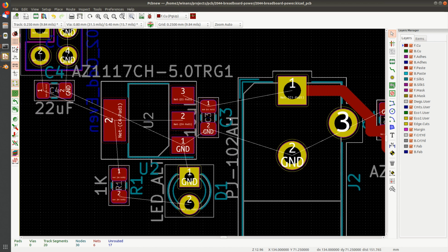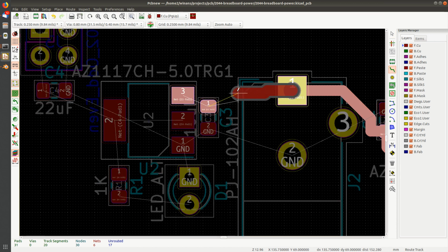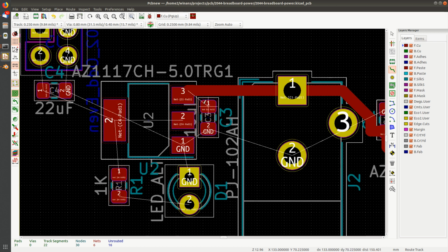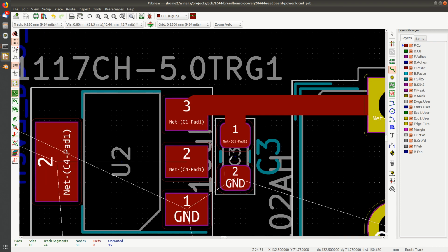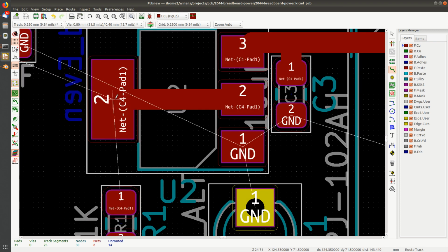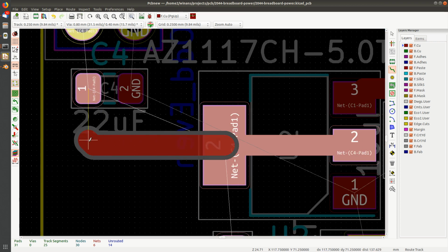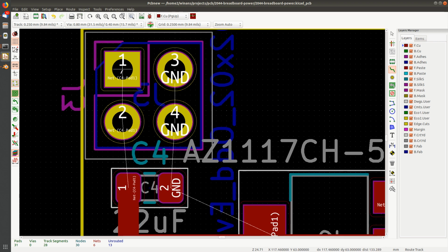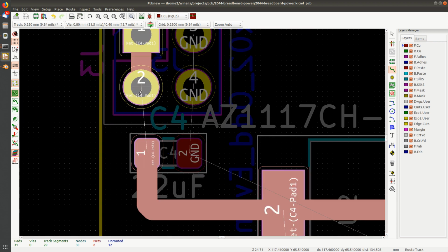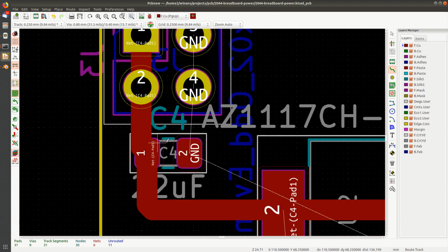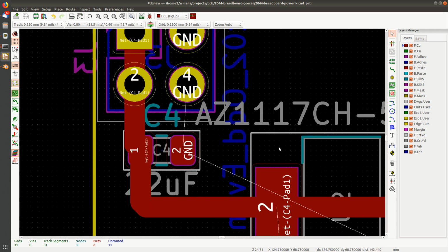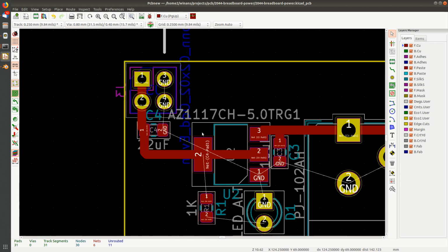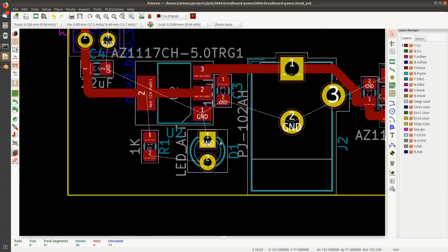So let's do the other regulator now. Boom, boom, boom. Well, maybe I'll go to here first, and then I can go like that. That's fine. Depending on what you're doing, a lot of circuits really are pretty reasonable, and you can be pretty sloppy with it. When you're dealing with big fat traces for power, it's DC, there's no AC component really to these signals, so it's okay. Just get them connected and they'll be fine. It's just the power.